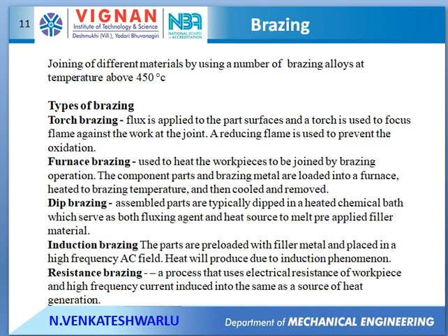And undercut, where some groove is formed, and incomplete fusion, where some portion of the weld bead is not completely melted. These two defects can be rectified by taking the optimum amperage and optimum weld speed. Next, hot crack can be rectified by preheating. Cold crack can be rectified by a suitable heat treatment process.